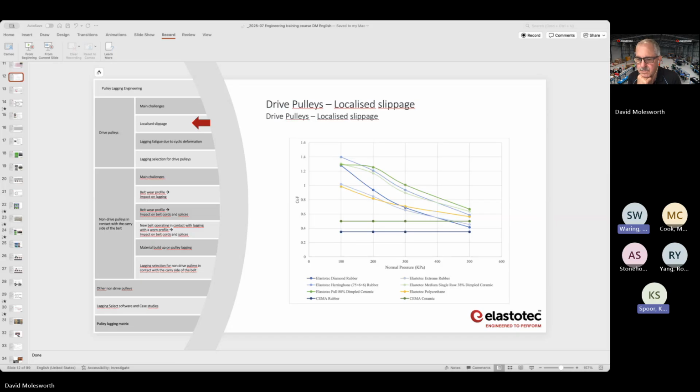So there's no recommendation, but of course we think under normal operating and normal start you should have no slip. But then if you had something like a block chute or a flooded condition, you'd probably allow some slip. But she wouldn't be drawn on what we should use. She was saying, well, you need to figure that out for yourself. But the tool is there to figure it out. I understand it now. Yeah, okay.